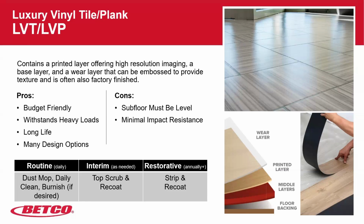The floor must be level because, especially if you're doing the sheet LVT, you can really see the undulations in the concrete and the imperfections, the cracks and stuff, if it's not level. Now, also a con about LVT is that it's not very impact resistant. If you drop something fairly heavy on LVT, it's going to make an impression in that floor that you're not going to be able to recover from. So those are some of the challenges that you have with LVT, and we see that going more and more into commercial every day, into grocery, into retail, and other settings.